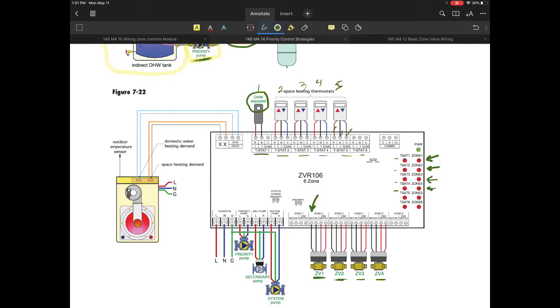Now, these are on the 4 zone valves that are listed down below here. Every one of those zone valves is considered a 4-wire system, and you'll notice that zone 2 is going to be powering the motor of the zone valve. So when that gets powered and that valve goes to its full open position, that completes the circuit and it essentially will close the end switch.